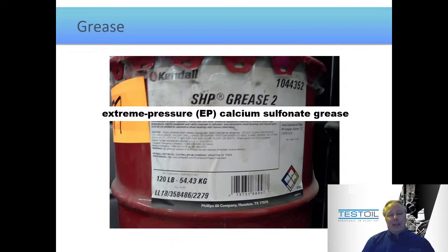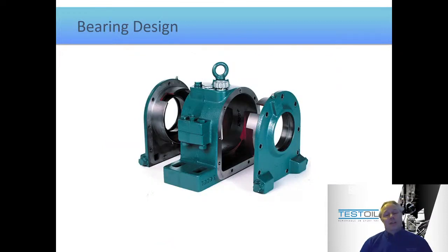That explains the calcium. That explains the phosphorus. The fact that grease mixes in with the oil would explain where calcium and phosphorus would come from. And if it's only a few drops of grease, it could explain why the viscosity didn't change. But you're wondering, how does this all mean that the bearing failed? Well, the last thing I need to show you is a picture of what the bearing housing would actually look like. This is the exact same brand of bearing that was used on the report.